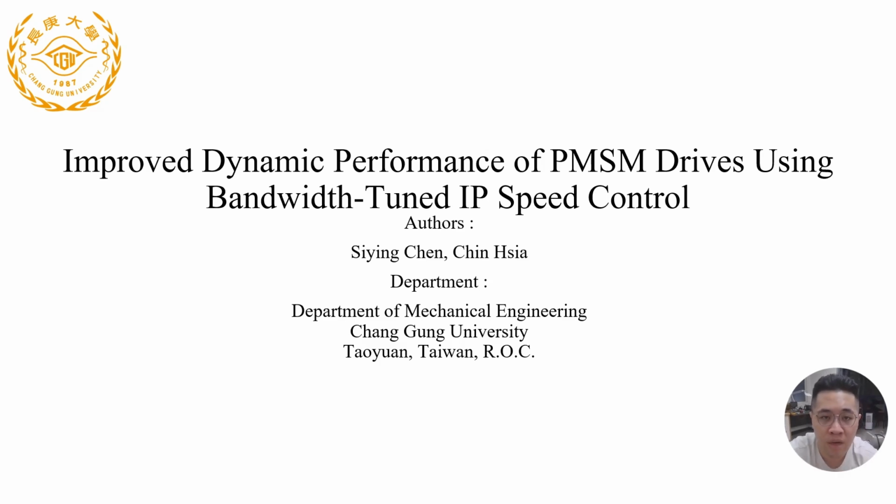Today I will present my work titled Improved Dynamic Performance of PMSM Drives Using Bandwidth-Tuned IP Speed Control. This will focus on the speed control of a permanent magnet synchronous motor drive. The main purpose is to improve the response speed of an IP speed controller while keeping its low overshoot characteristic.